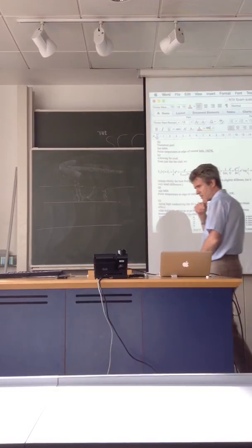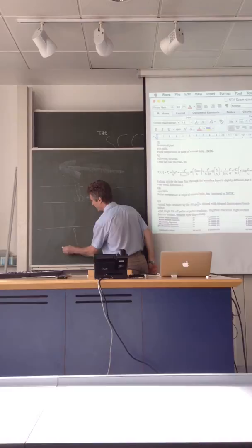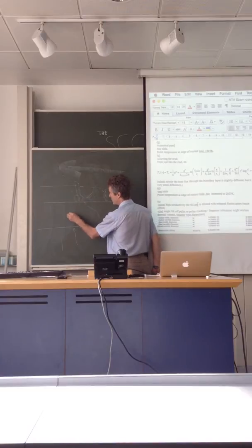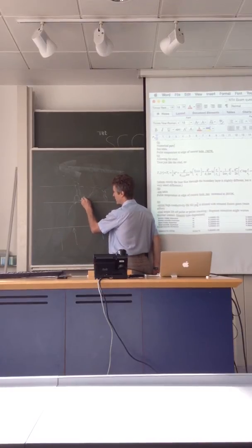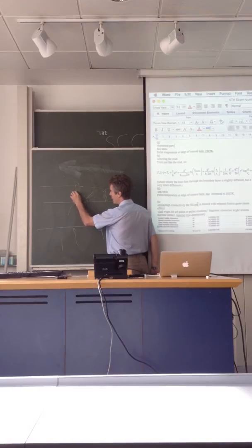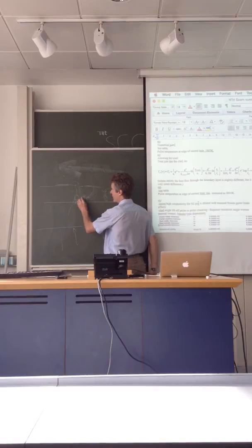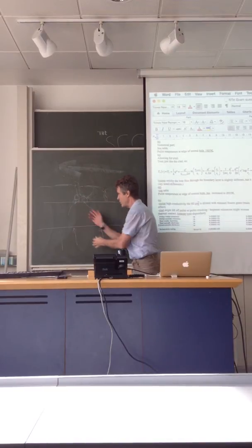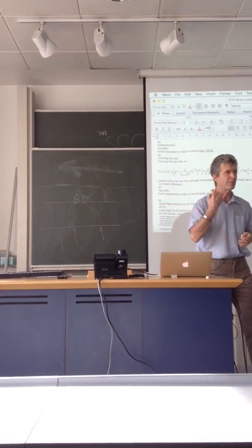Because the heat, it turns out, is coming in more or less uniformly from the pellets below, you end up having a very big fraction of the heat coming into just this bit down at the base of the chimney. So it comes in and sort of turns sharp here, and you end up with almost no heat being transferred from there, and almost all of the heat from that whole region turning into vaporization of the water down in the bottom of those chimneys.